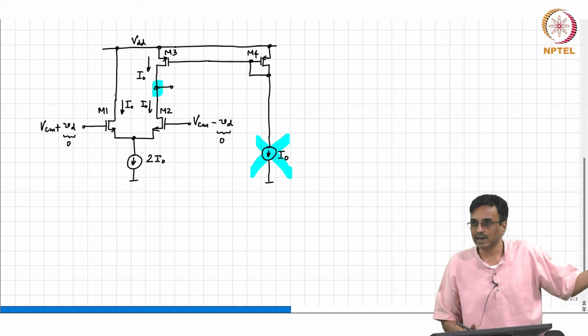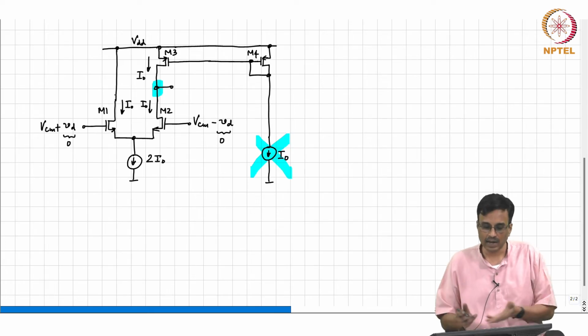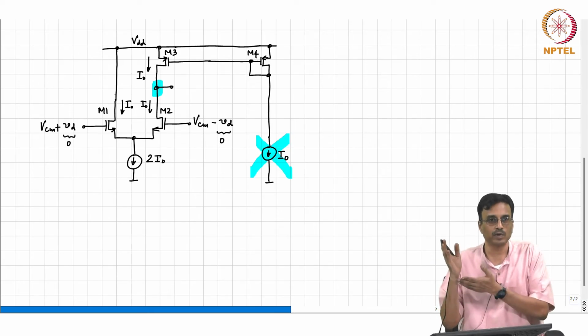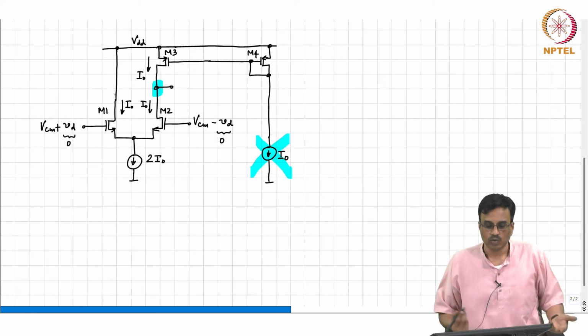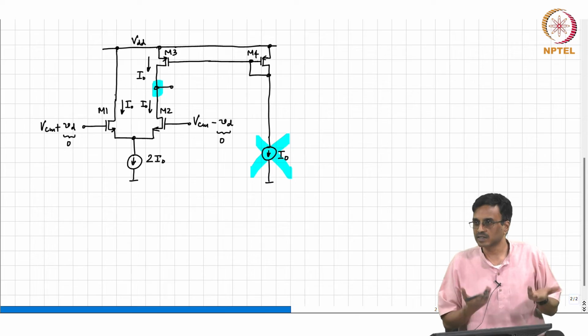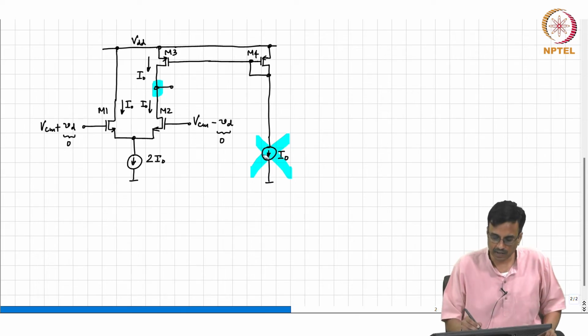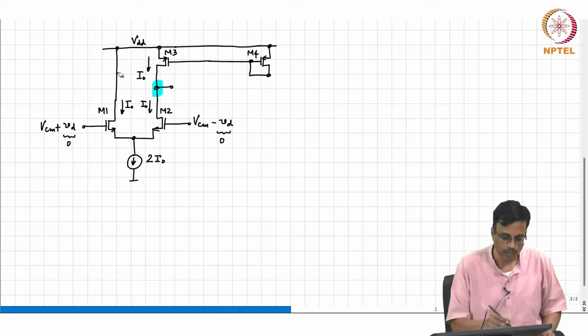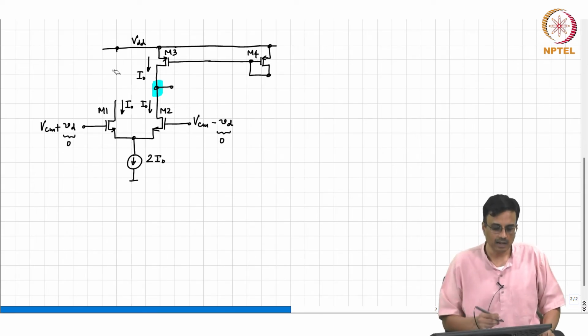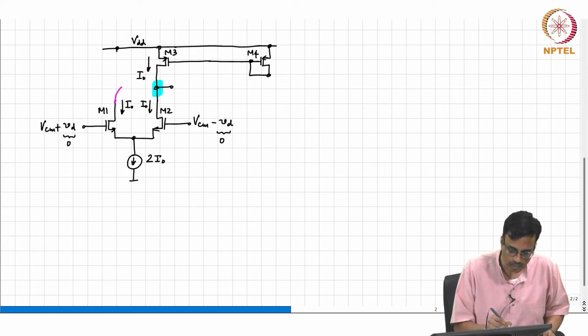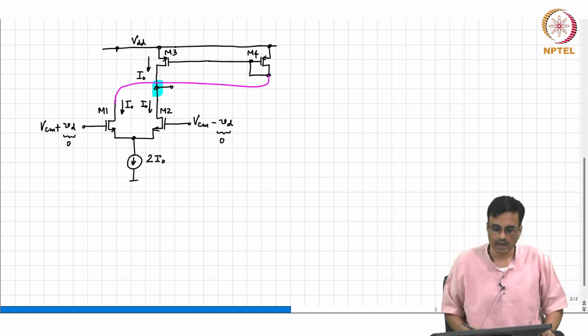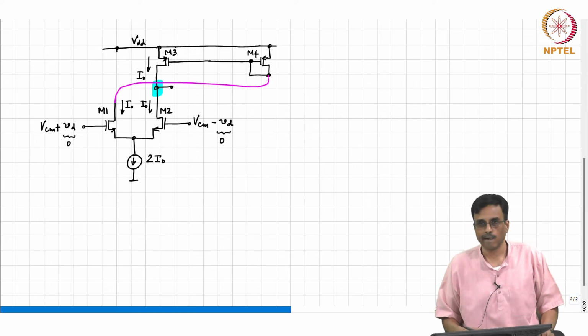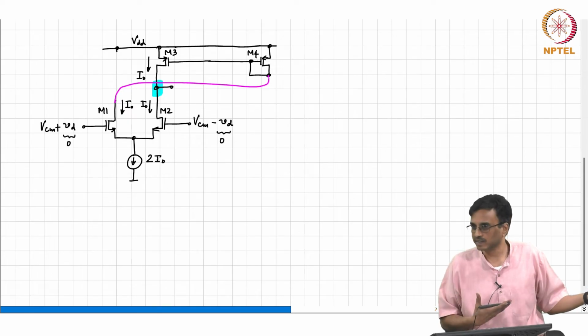So M1 is sitting idle doing nothing, correct? Why get one more current source and put it through M4? M4 needs a current I naught anyway, and this M1's drain current is doing nothing. So the smart thing to do is to get rid of that extra I naught, break the connection here, and connect that guy there. Does that make sense? This is not rocket science.